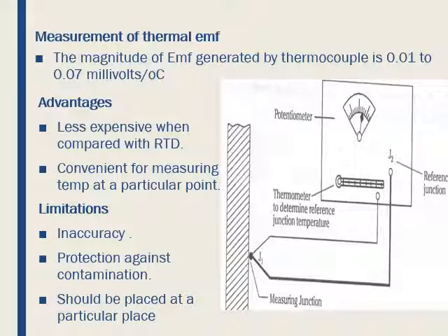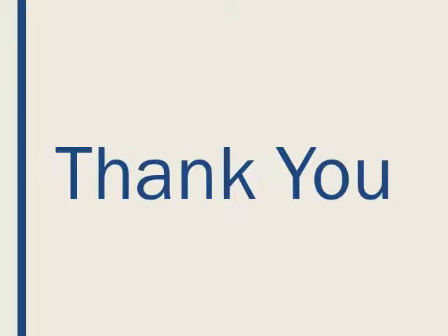There's one more resistance based temperature measurement device, the thermistor. A thermistor is a type of resistor whose resistance strongly depends on the temperature. The word is a combination of thermal and resistor. A thermistor is a temperature sensing element composed of sintered semiconductor material and sometimes a mixture of metallic oxides such as manganese, nickel, copper, cobalt and ferrous, which exhibits a large change in resistance proportional to a small change in temperature.